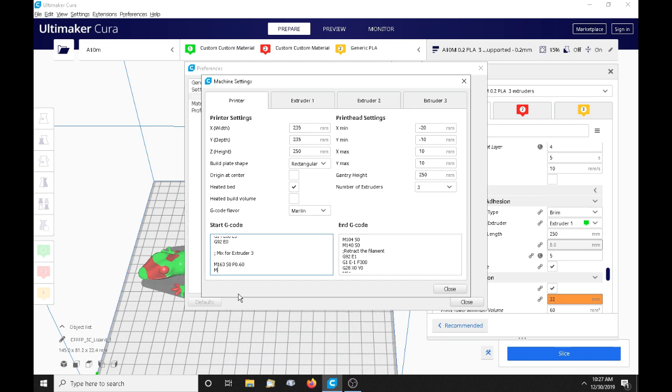So we need to set extruder 2, or in the G code, S1. The percentage of this one obviously must be 40%. If you're using an A10T or A20T, you'd have to add your third line of M163 S2 and its percentage, and again all three have to add up to 1. So we have our percentage set.